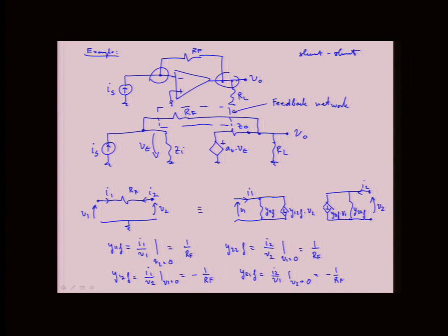So that's the complete network model, like mapping a simple series resistor into the Y parameters. However, this now gives us a notion of how this resistor actually loads both the output of the amplifier and the input of the amplifier. And we can go and from here really clearly figure out what A is and what F is. So that's the whole point of this exercise.